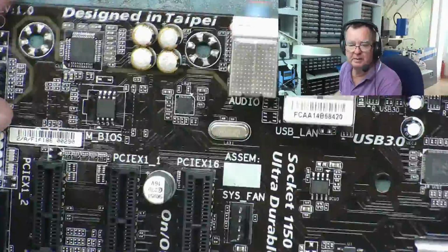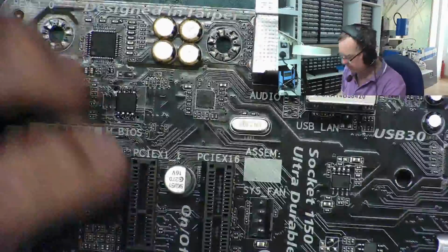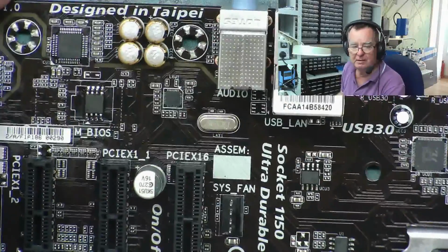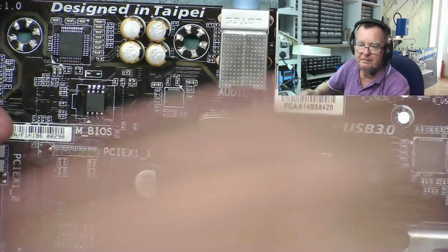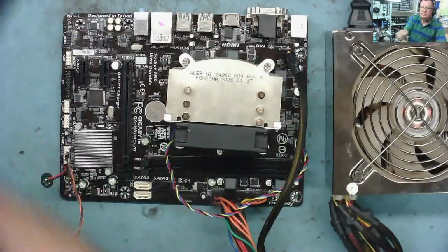There's our BIOS chip then, quite neatly soldered back on the board. Hardly even notice it had been taken off. So the little dot at this end to the little notch at this end. There's no backup BIOS that I can see on this motherboard. So let's see if this actually made any difference at all. Let's try it then and see what happens.